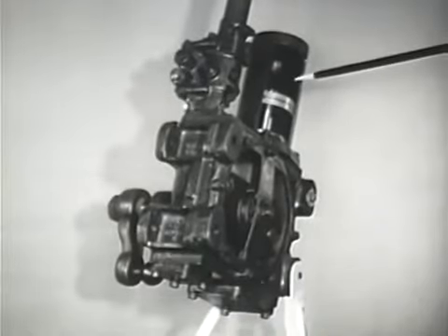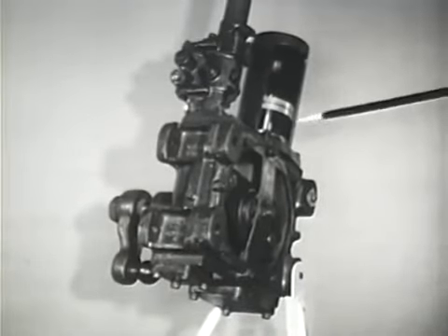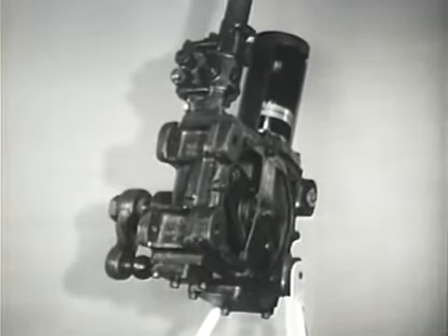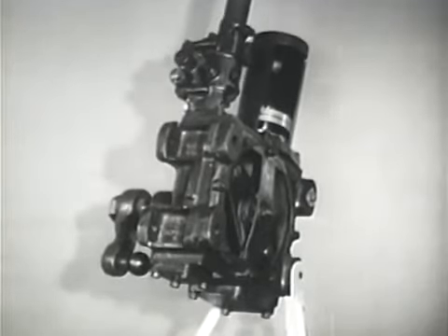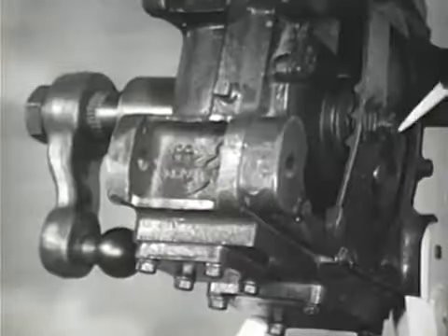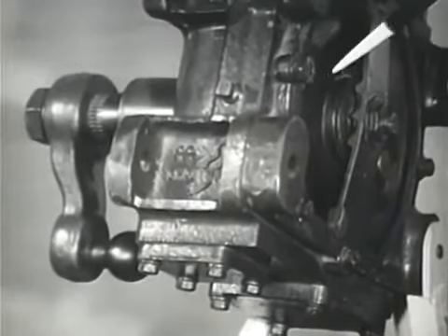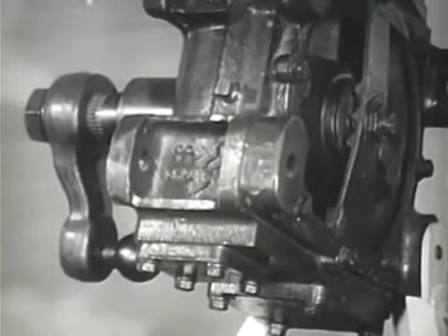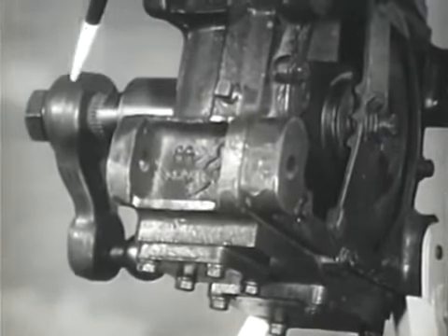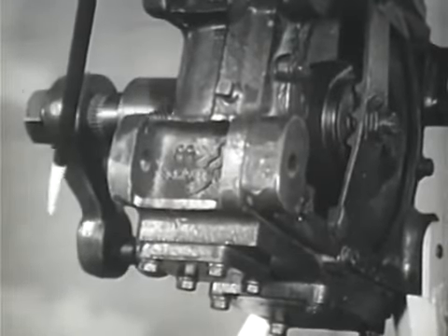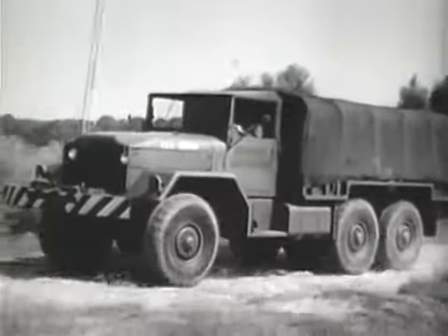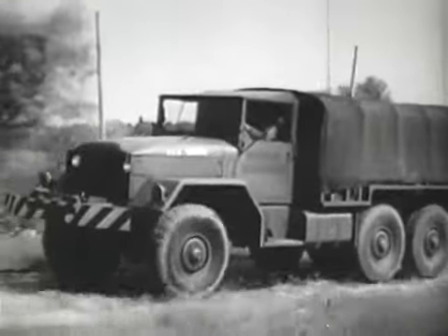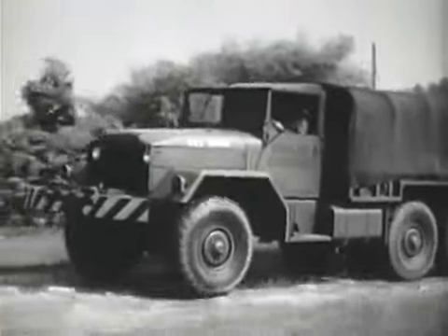The slightest movement of the cam results in a pressure differential in the power cylinder and an applied force on the Pitman arm shaft and lever and the Pitman arm. The hydraulic steering system resists shock and kickback through a reverse action in the power cylinder.